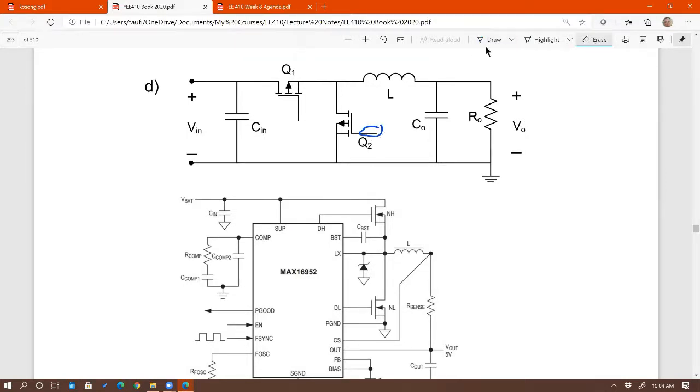So this is connected to the PWM controller. You have a driver circuit basically. If I were to draw a driver circuit as PWM out, you can connect it to there. So instead of having a diode there, it's actively controlling it like an active rectifier. That's correct, yes. Just keep in mind that in order to control a MOSFET, you need a gate-to-source signal. For this one, you just connect this gate to a controller right there. Does that answer your question?